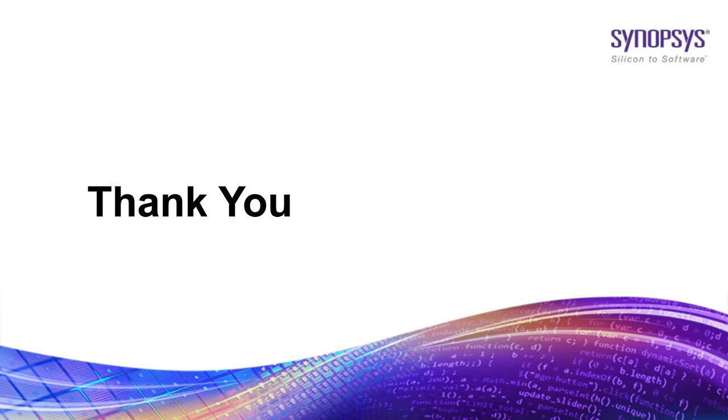I would not think that there are different requirements for analog versus memory versus logic and so on. In fact, the functional safety requirements are at the chip level, because the chip is manufactured and has to meet the requirements of functional safety. What we do at the IP level, we do the preparation for that. So they are prepared for the functional safety. Of course, they are not manufactured yet as IP. When we supply those IPs, they are ready for the ISO 26262 at a certain ASIL level, but they are not manufactured yet. Therefore, they are not meeting that yet.